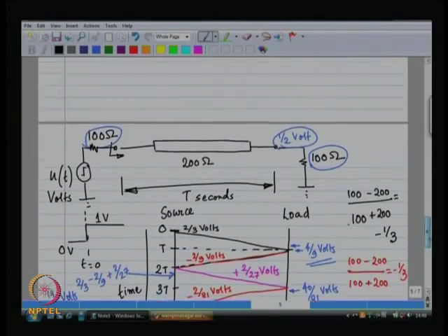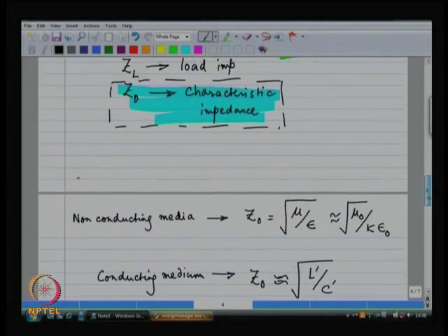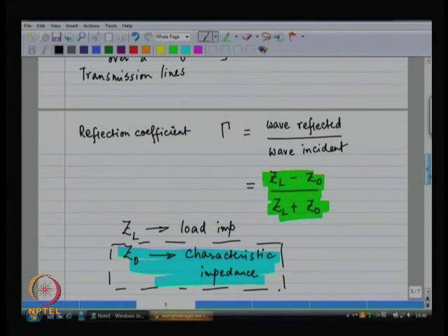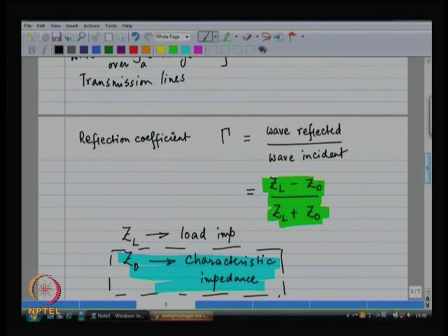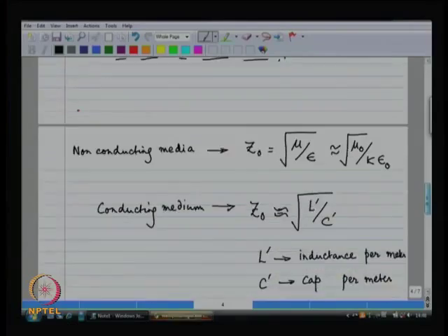If you know how many dB of loss you are having per meter or per kilometer, then it is just a simple addition on top of this, right. The other thing that changes when you incorporate loss is that this parameter Z naught no longer remains a real number. It could very well be a complex number. ZL, ZS, these could also be complex numbers, in which case gamma itself is a complex number,